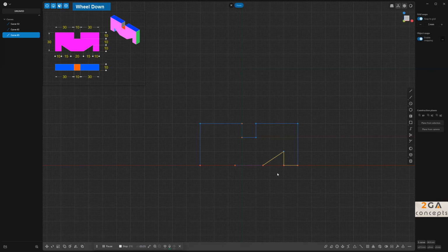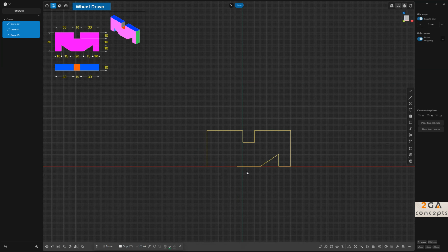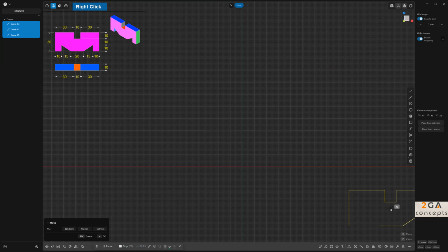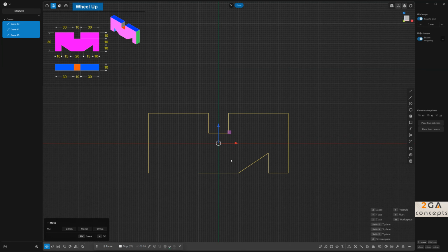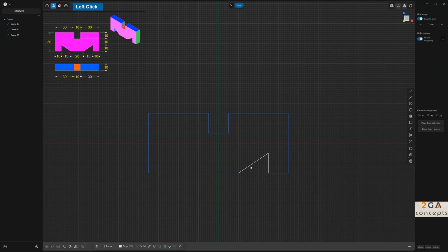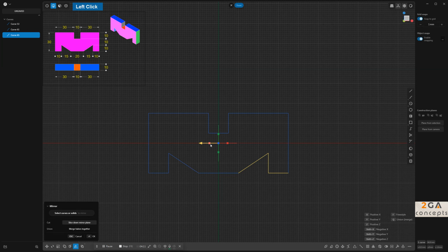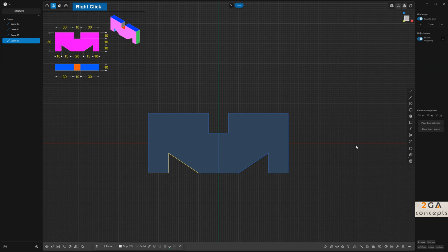So I'm going to enable the line selection with 2 and take all the curves and go for G, F, you click anywhere, and F again, and everything is centered to the origin. Now I'm going to take this bit and mirror it on the other side. So Alt X, there you go, and right click to confirm.